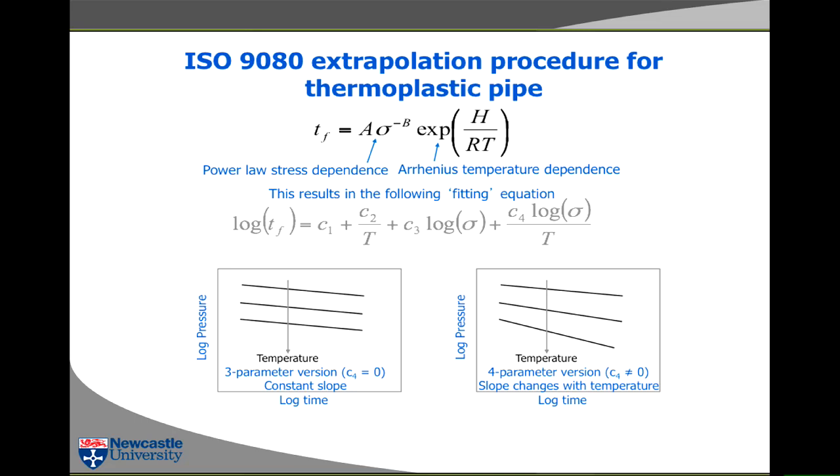I'm not going to derive it, but if you have any process which is temperature dependent, then if you do it at one temperature, and then you do it at a second, say, higher temperature, then the rate at which the thing happens changes by this factor. And it's called an activated rate process.